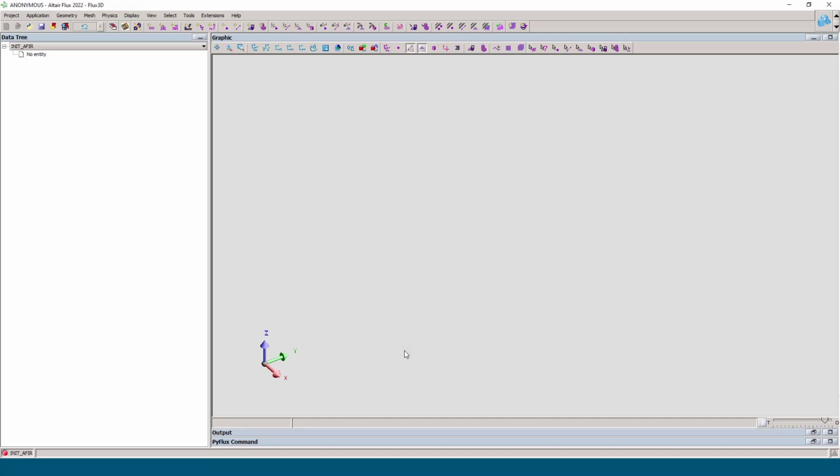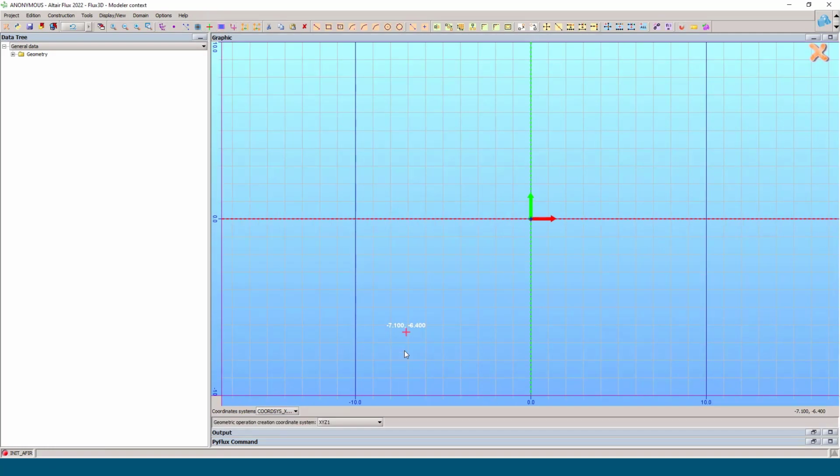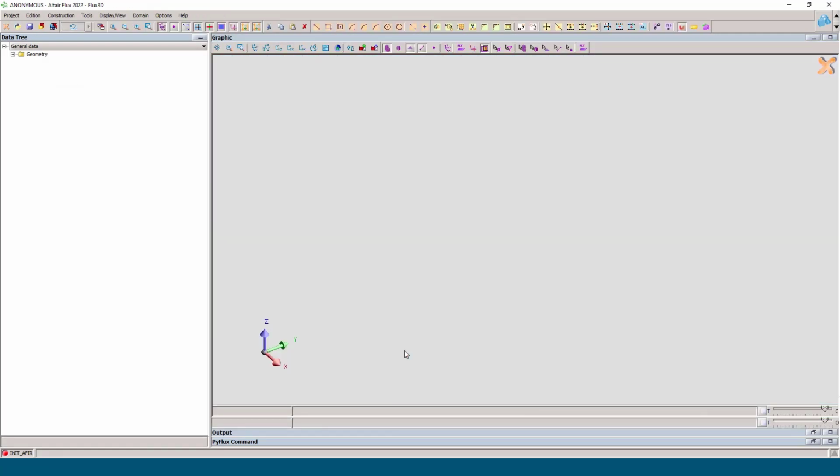Clicking on OK, the macro starts and builds the parametric model of the axial flux machine with the values that we entered. After a few seconds, the sketch context appears in order to create the two parts of the motor, starting with the rotor one. We can see the building of the magnets, of the rotor yoke.